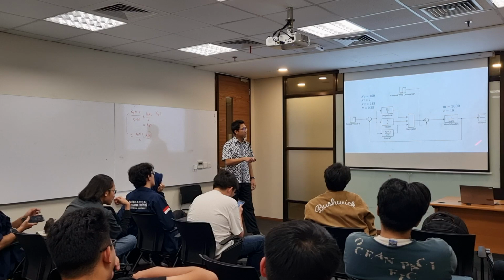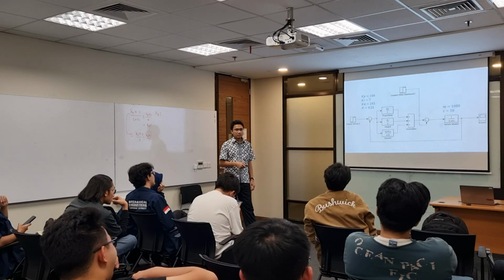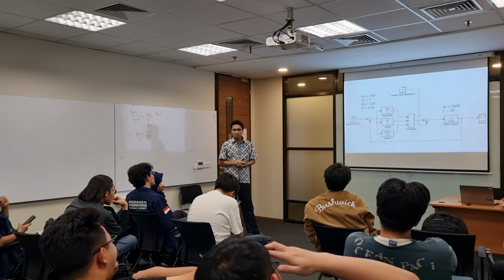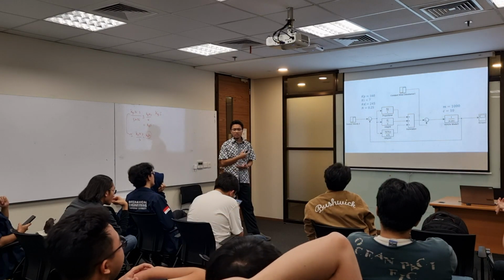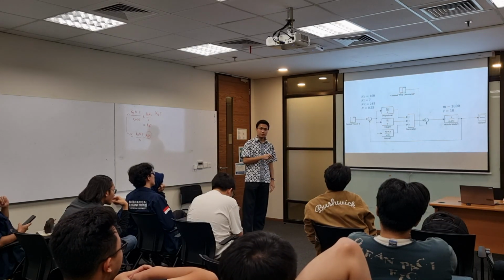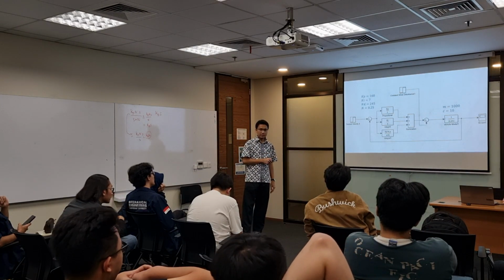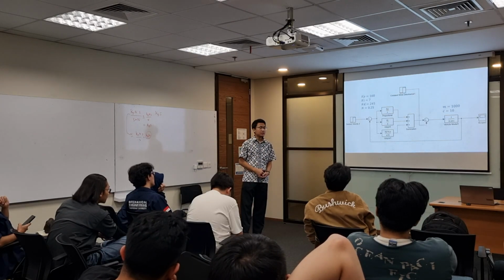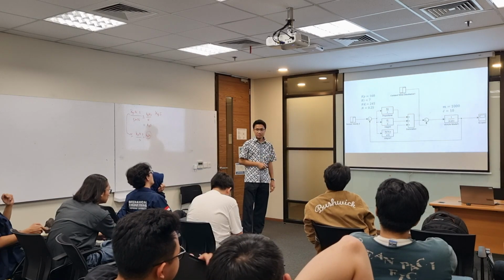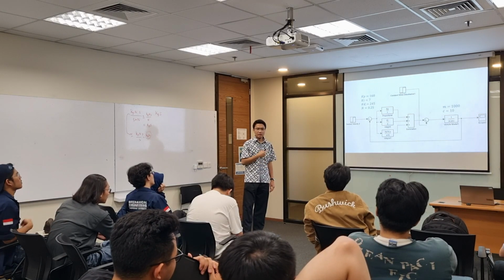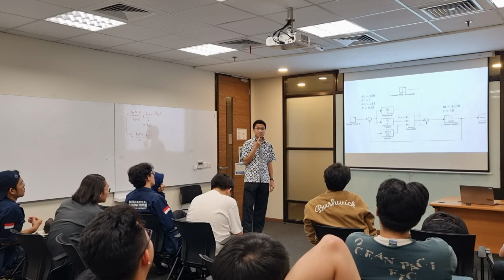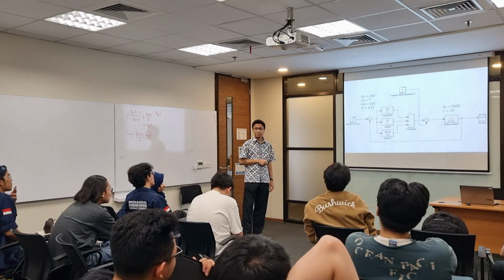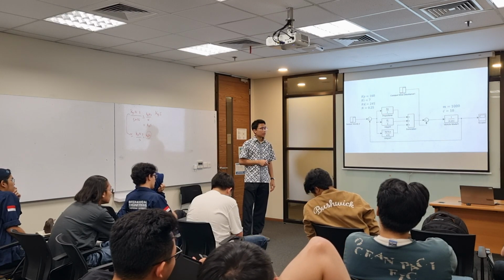Logically, what can you see from this system? Do you remember what this system is about? This is a car, speed control of a car, yeah? With wind disturbance, okay. The disturbance is still there, yeah? So what do you think the integral control is doing there? Yeah, it is cancelling the disturbance. Why is it only the integral that does this?